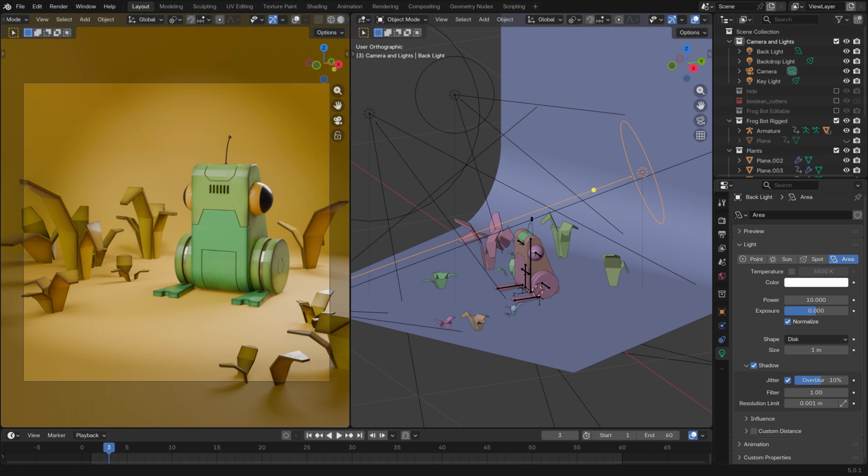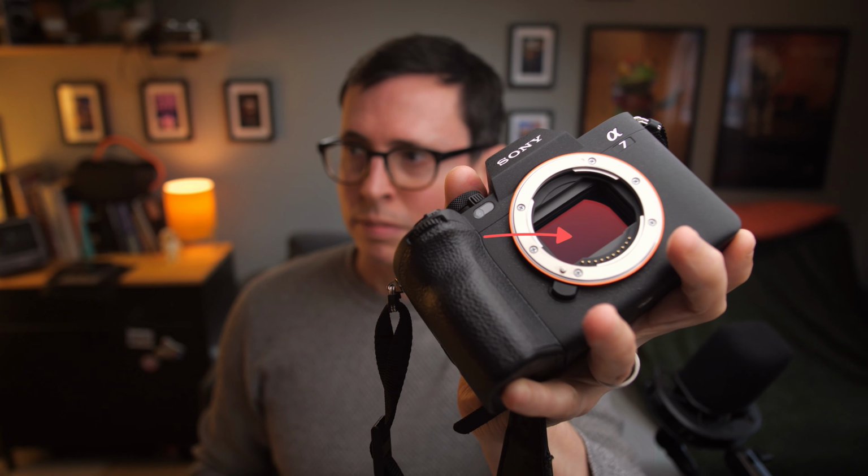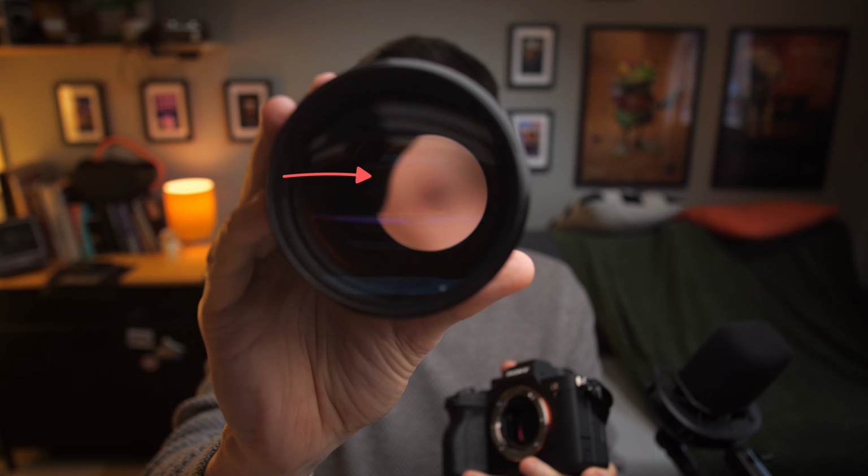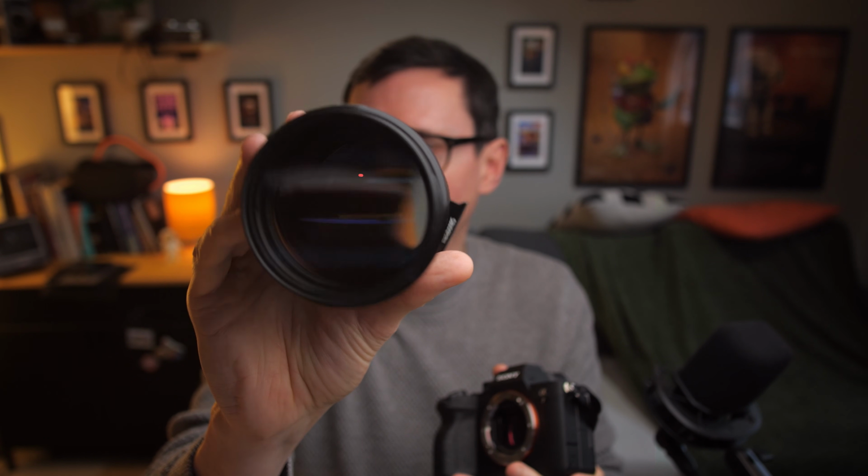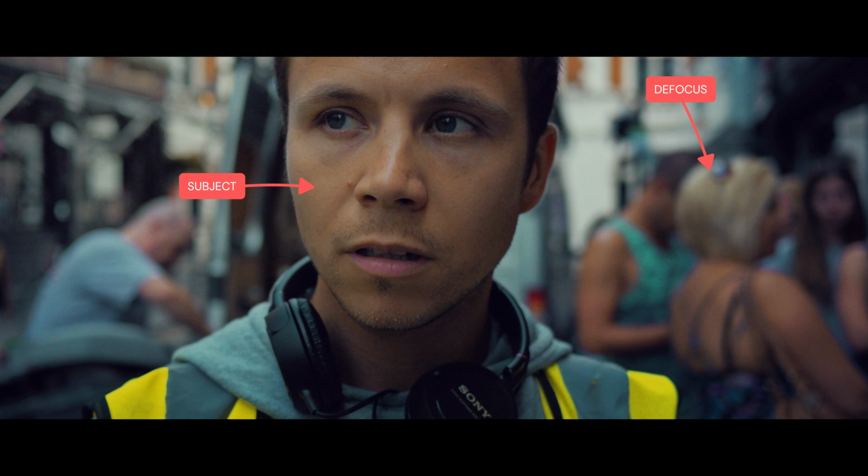Before we jump into the Compositor to add some effects, I think a really cool effect would be some slight shallow depth of field with our camera. Shallow depth of field is when elements blur depending on their depth outside of a focal plane or focus point. Accentuated with larger camera sensors or film backs and a larger lens aperture or opening with a long focal length, being more zoomed in. It is used a lot in photography and cinematography to isolate subjects.